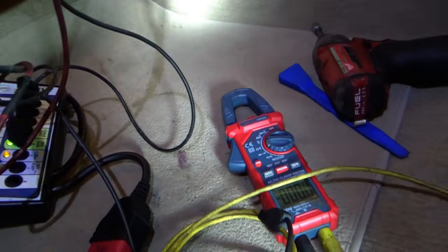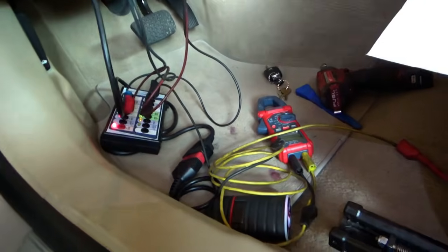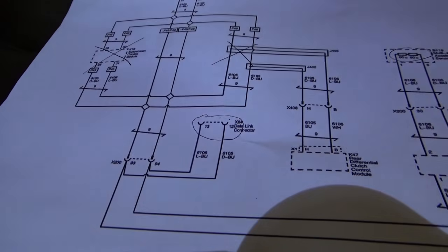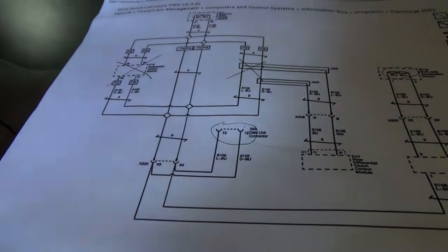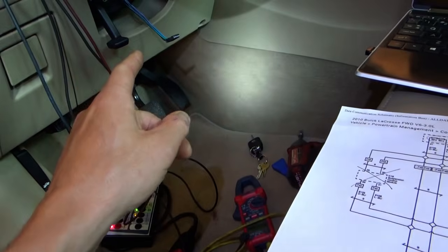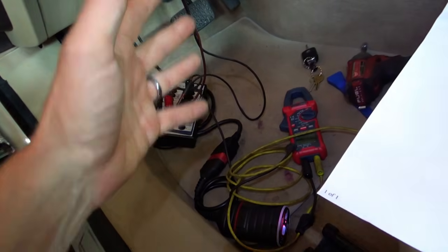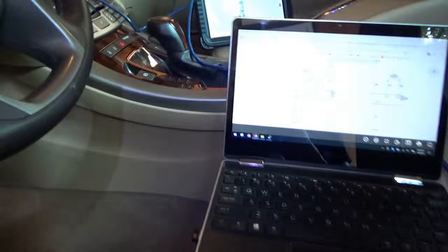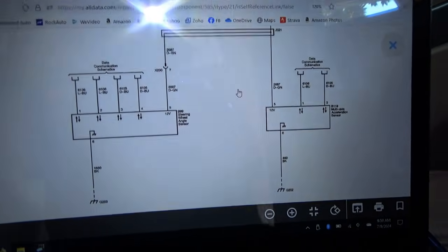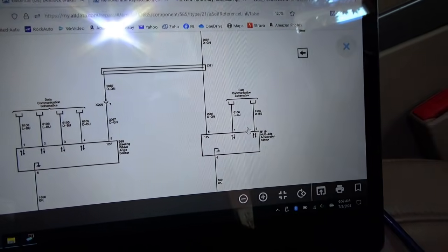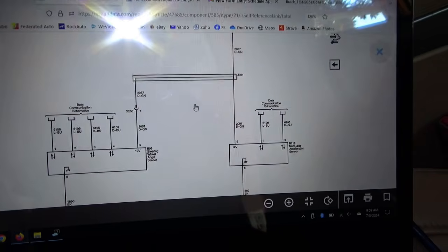What's the next step? Well, let's use a small test light and provide 12 volts to that green wire, from battery positive to the green wire. Maybe there's a short, and if it's pulling that line down, potentially the EBCM could have a current limit in here, and then the voltage doesn't even make it to these two sensors.